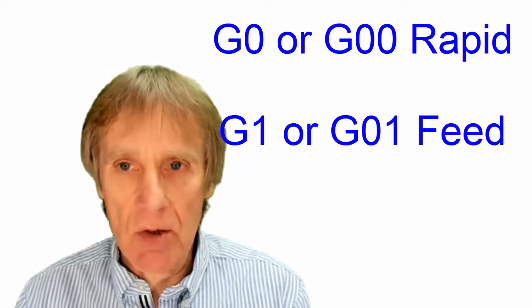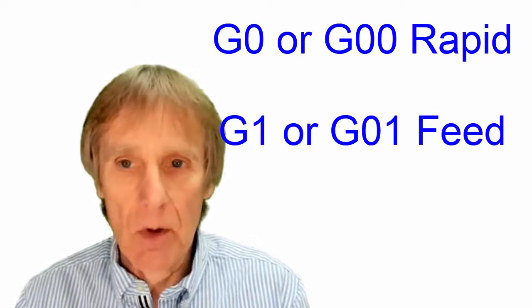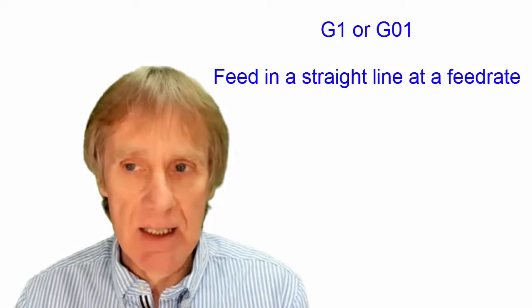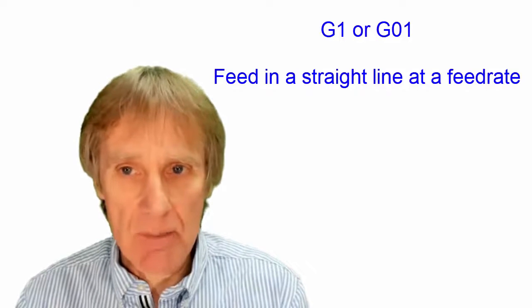And then the other one I'm going to use is called a G1, sometimes known as G01, or G1 as you'll always hear me refer to it. This is a feed, and it means feed in a straight line. So the axes that you command will feed at a feed rate. So if I gave it a feed rate of 300 millimeters a minute, it will feed to this position at 300 millimeters a minute. So it's feeding at a commanded feed rate. So I'm telling it how fast to go. And I'm going to use those two simple G-code commands to drill myself 4 holes.